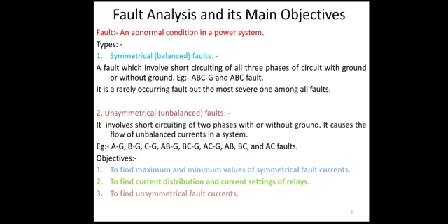A fault which involves short circuiting of all three phases of a circuit or a system involving ground or without ground are known as symmetrical or balanced faults. Example, three phase to ground fault or three phase fault, ABCG or ABC fault. Basically, it is a very rarely occurring fault, but it is the most severe one among all the types of faults.